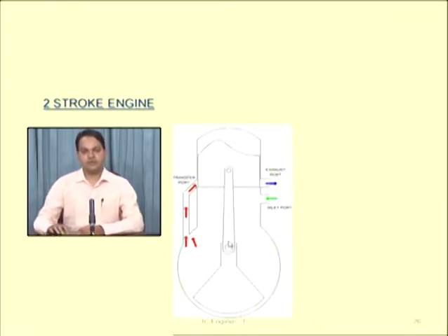So now let us understand the process is same. The suction will happen, compression will happen, expansion or power will happen, exhaust will happen. But how it will happen without valve, let us understand. At this particular figure, if you see the bottom portion of my piston, this line, it is covering exhaust port. So flue gases cannot go out as it is in off condition, closed condition.